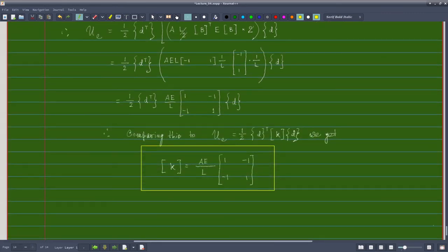In complicated elements like 3D or 2D elements, if we try to do the numerical integration in terms of the absolute values of the nodal coordinates, it will be more costly. Another advantage of natural coordinates is that for every element, when finding the stiffness matrix, those integrals remain the same if the element type is the same. So we need to store them only once, and that will reduce the computational cost.